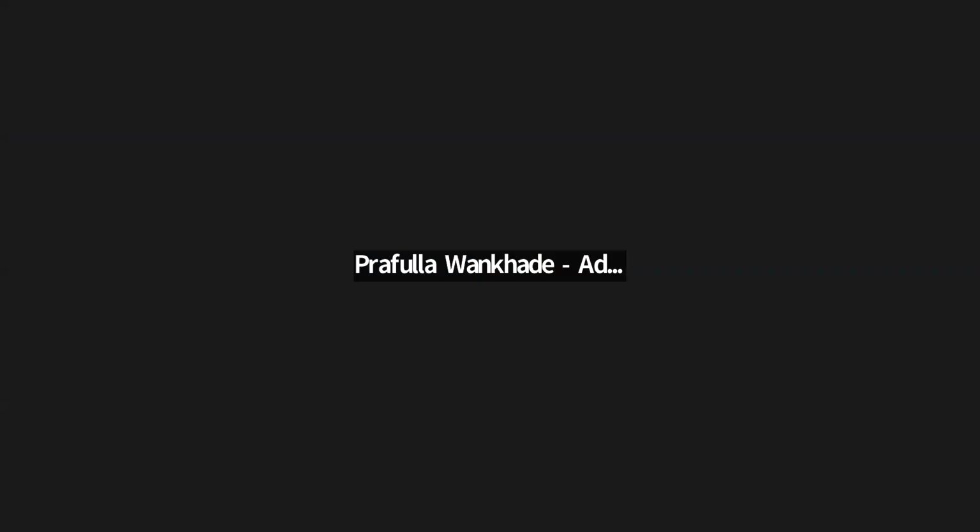So, Praful, you can go ahead and ask your question. Sir, my question is, you said earth electrodes are not required and we can have MET. But finally, MET, as you showed in one of the pictures, consists of a mesh. We used to do a mesh kind of earthing system with a grid of earth strips with two to three earth electrodes. So the same concept is used in MET also. It is nothing but the same thing, or is MET without any earth electrode at all, using only the existing metallic parts of the building?